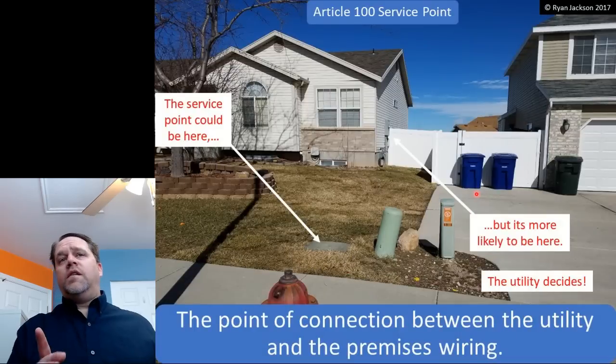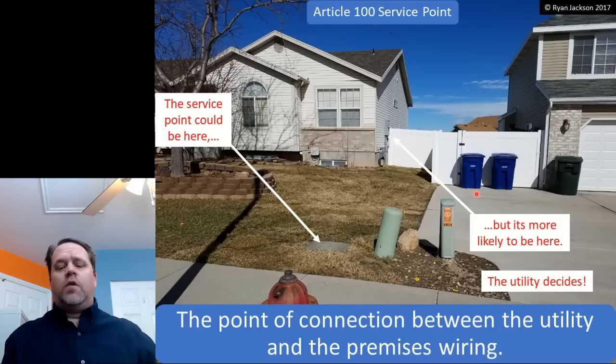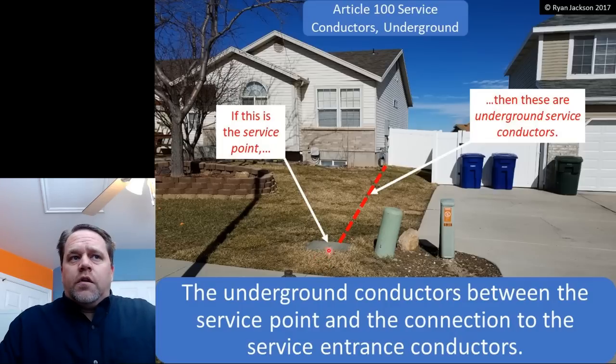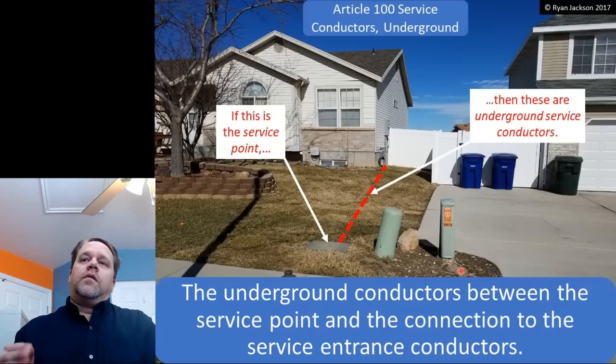So the service point is really where the NEC starts. Anything upstream of the service point, we don't deal with it. That's utility stuff. If the service point was this underground junction box, then that's where the code would start. The conductors that go from the handhole enclosure to the meter would then not be a service lateral. They would be underground service conductors.